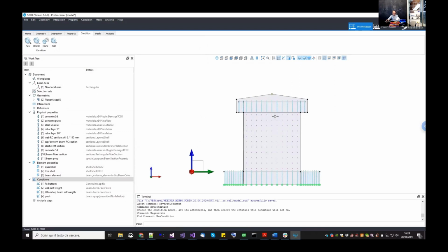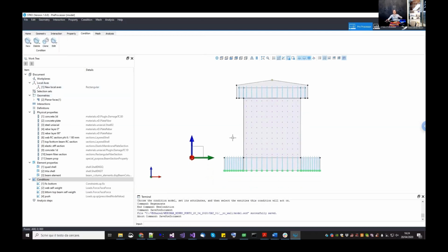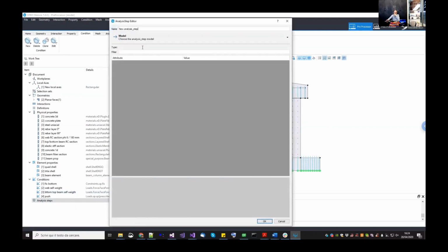We just need to go to the analysis steps. So let me say 5 once again. As I did before, the analysis steps define the way you go into the analysis. So as a rule, I always use the recorder as a first step. This is not necessary, but you can place it later on. But the recorder will start recording only the things that are defined after him.